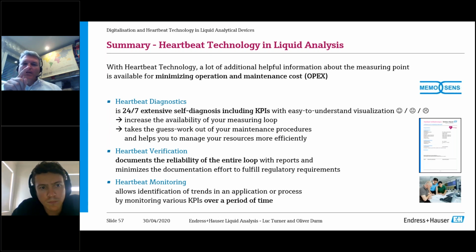If you click on that, it will open a chapter where you can get all these guidelines, how to access the data via HART, via Profinet, via Profibus, via Modbus, via Ethernet IP. There are separate documents which document for each digital fieldbus how to access this data. So the programmer will know which register or how to get these things via AOP file, can I access them and integrate them into my PLC. Brilliant.